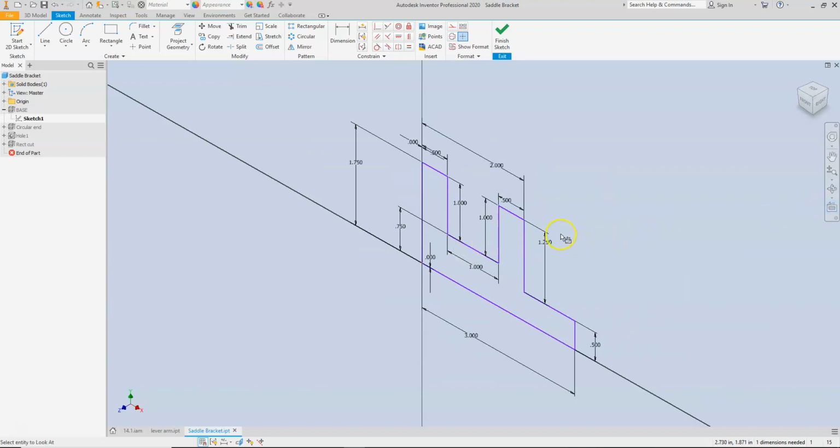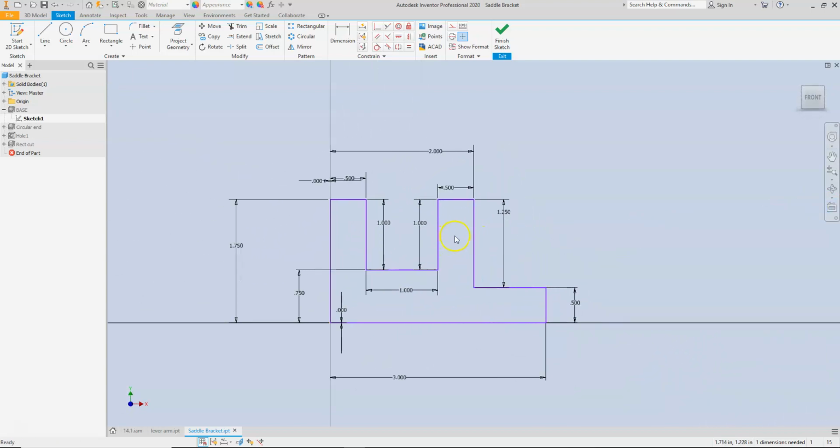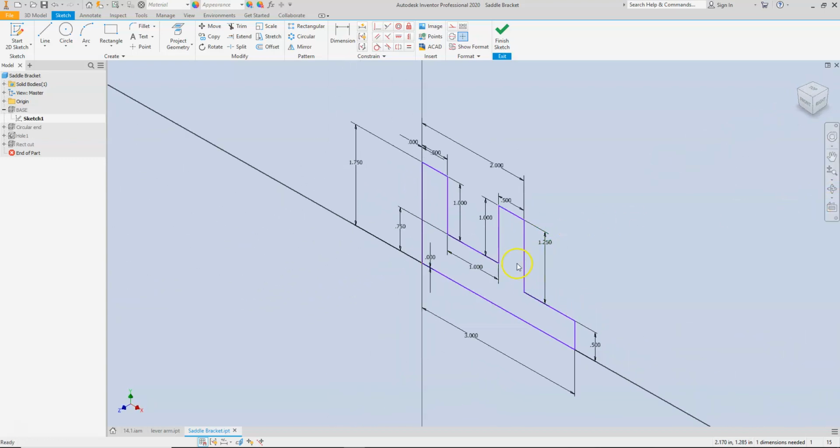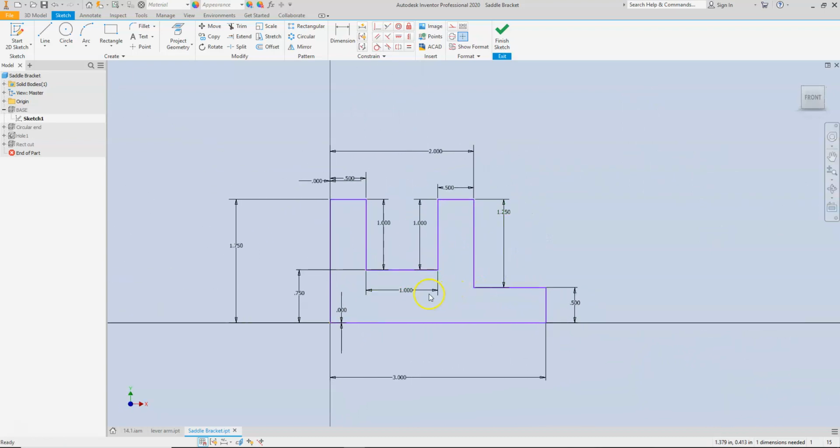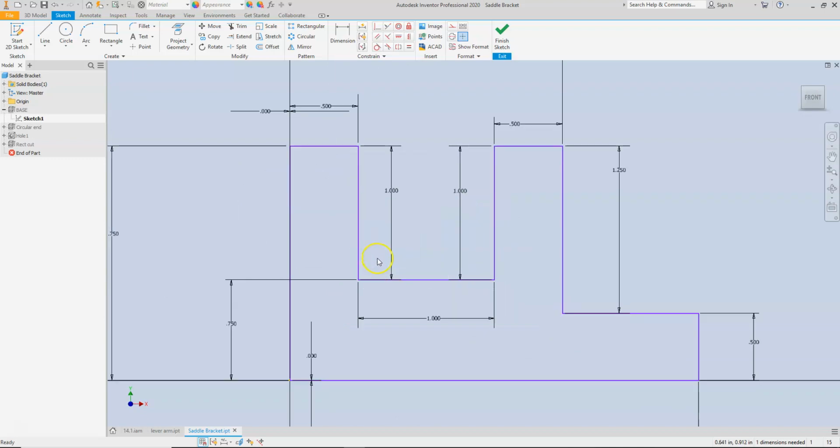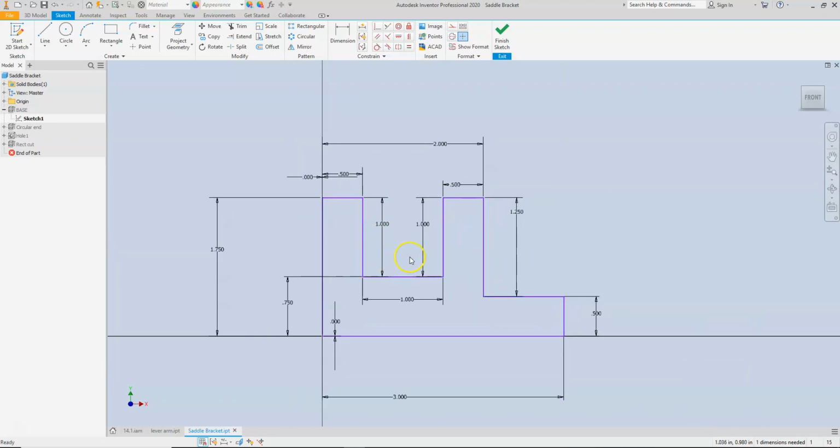If you click on the look at button and then pick a line that's on your sketch, it will go ahead and reorient your screen to make it flat with whatever XY plane or whatever plane you're working on. So that's the look at button, and remember the F6 button is also another button that will toggle that and have the default for the isometric. So two toggle buttons I don't know if you're totally familiar with, but it's good to know that they're there when you're trying to manipulate your drawing and get it to orient in the right direction.